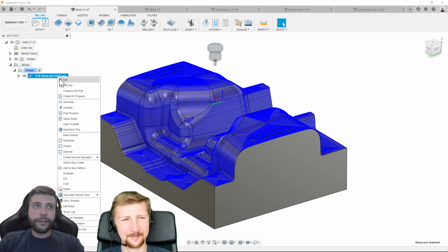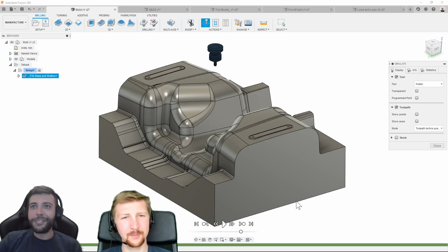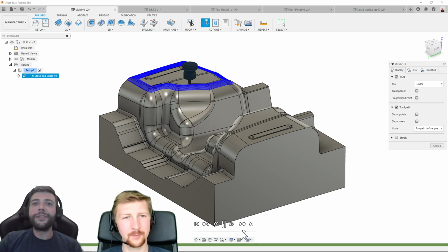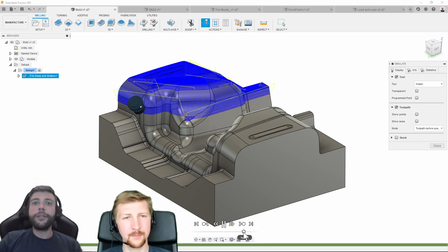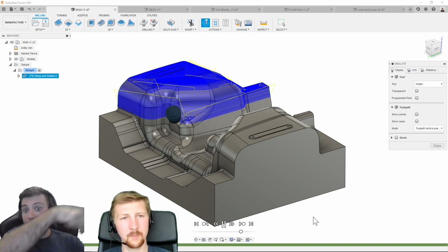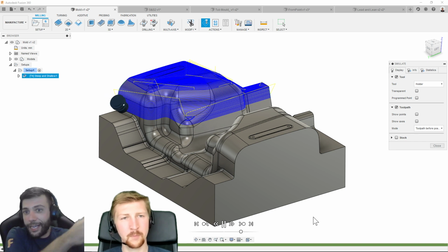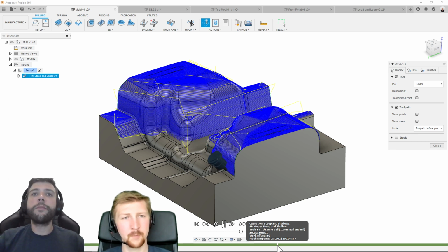Okay? And we're going to quickly simulate this to show you that I'm not lying when I say this is not an image. We're actually going to speed things up a little bit. You see, it's ordered by top because I told it to start at the top. And you see, let's slow it down now, it's changed orientation and is staying at the orientation to stay there as much as it possibly can to maintain an excellent surface finish along that wall. It would be stupid to go back to 3-axis just for a little section of that pass to then go back to 5-axis and then go back and forth. Okay, you obviously want to minimize axis rotation as much as possible. Let's move on.